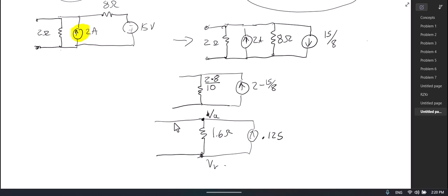So my current, as it's traveling along here, is going in this side, through the resistor, and down that side. And so I know that I equals VA minus VB over the resistance. This is the direction that the current is going, so VA is where the current starts from. Well, VA minus VB is exactly V open circuit that we're looking for.